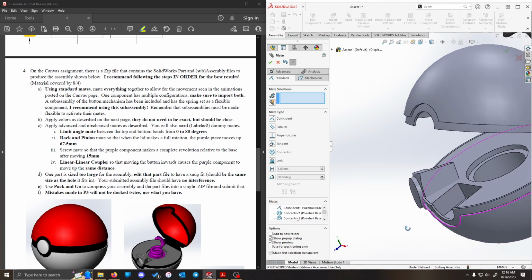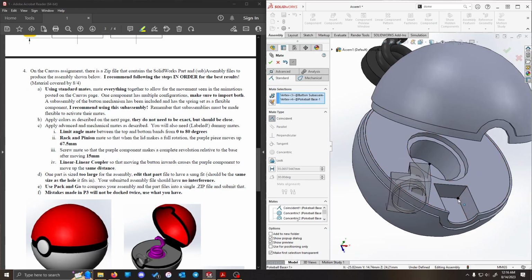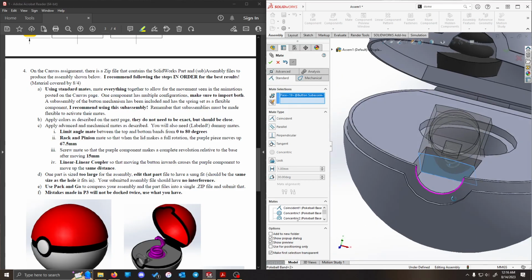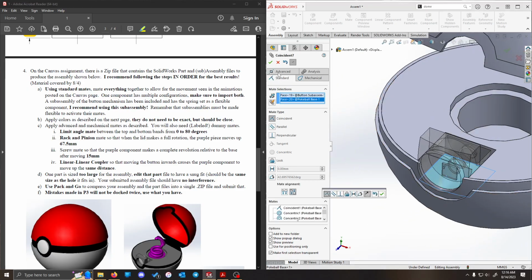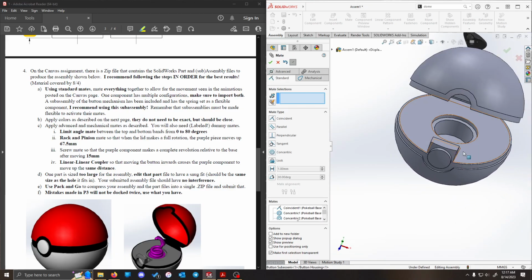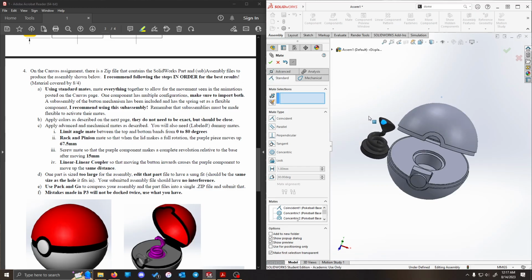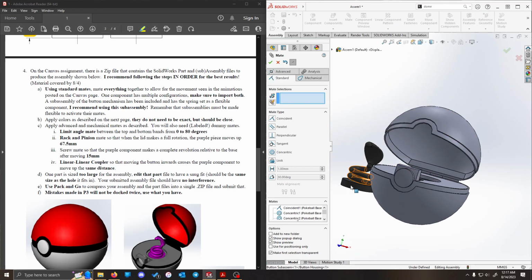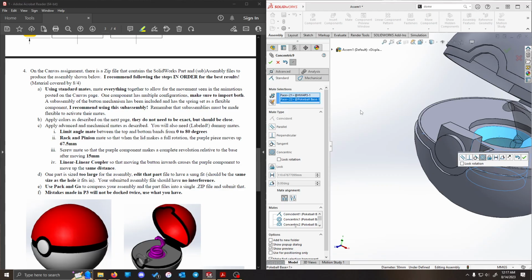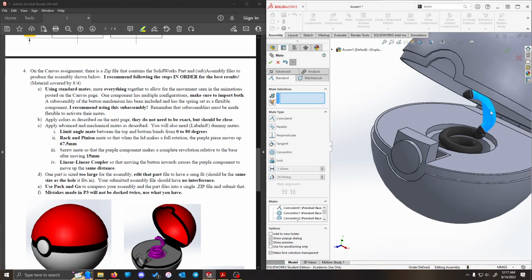Then we can grab that corner and that corner, make them coincident, and then the bottom of the button and the bottom of that cavity, make them coincident. Cool. Lastly, but not leastly, we have the actual snake itself. So we want the cylinder of that to match up with the cylinder of that. Keep those concentric, and that will behave the way we want.